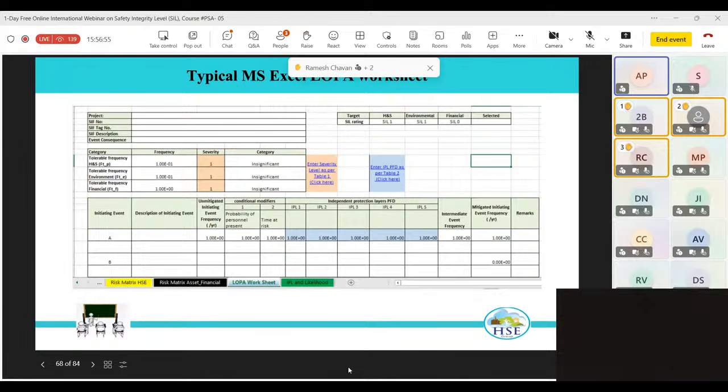In the available time and in the given limited LOPA worksheet, we can explain it to you like this, and this will be the final calculation. Say, suppose it comes to a risk reduction factor of 100. So now you have to decide that the PSHH loop will have to be designed for a risk reduction factor of 100. And what does that mean? So now you have to write a safety requirement specification for this loop. Okay. That safety requirement specification, Apurva will show you.